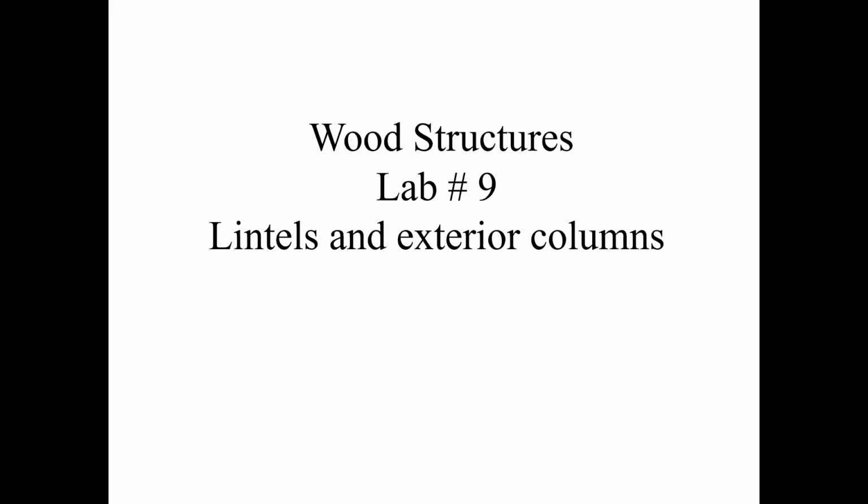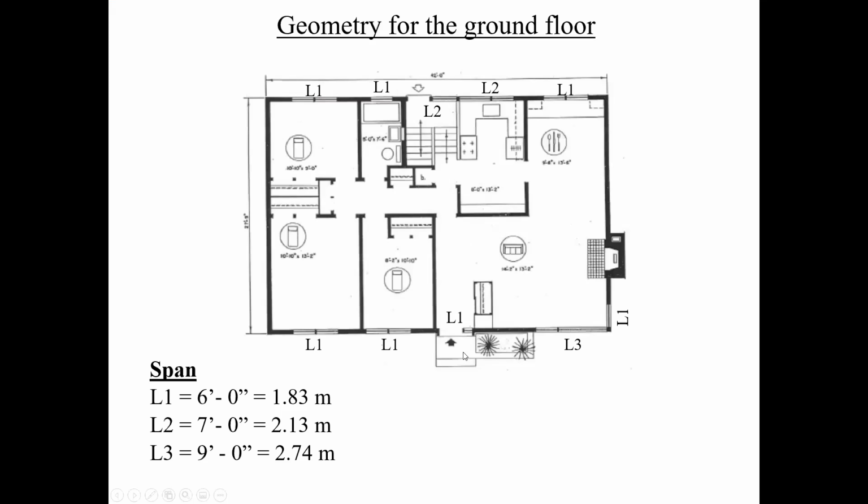Okay, so guys, we'll talk about the lintels and exterior columns, and now we'll be able to relate it to a floor plan. If you remember, this was our floor plan. Now guys, I don't know if you noticed this, but this drawing is approximately 1/8 of an inch equal to 1 foot 0 inches. Has anybody tried that? In other words, if you take your imperial scale of 1/8 of an inch, just check here if you printed this out, you have 42 feet. Anyways, I think that's approximately the scale of this drawing.